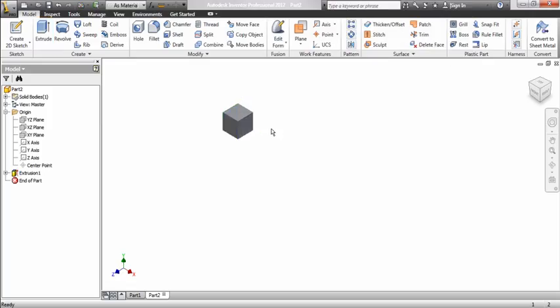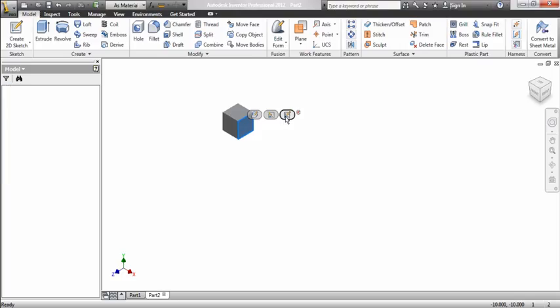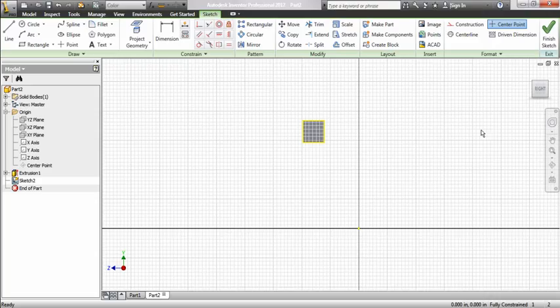So this concept I'm going to extrude several times just to show you how you can lock different pieces onto one another. And so if I want to continue this another 0.75, I can just click on this face right here, make a new sketch. This is the third button over. It says create sketch, and now I've got my block.